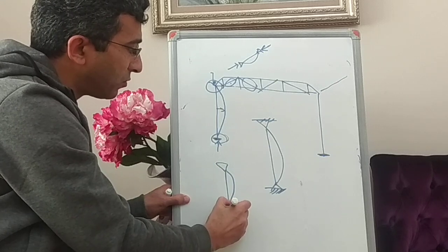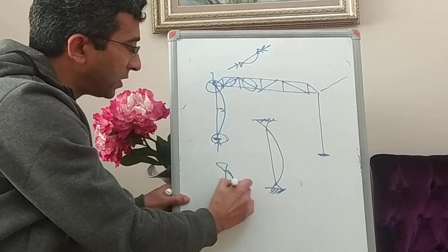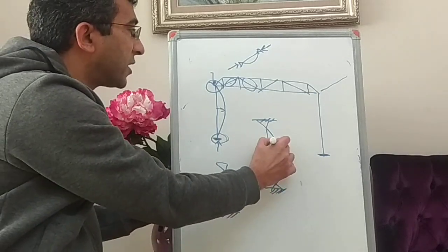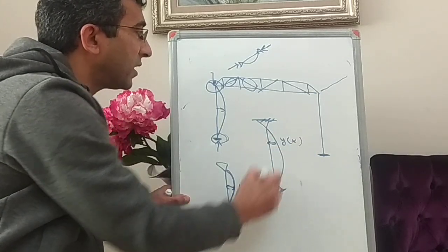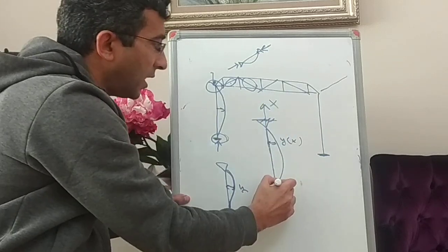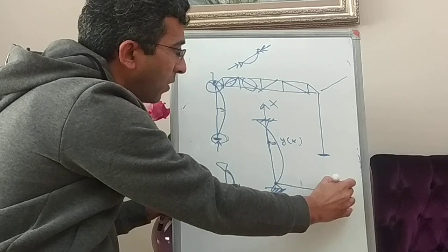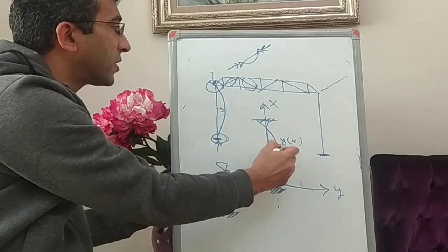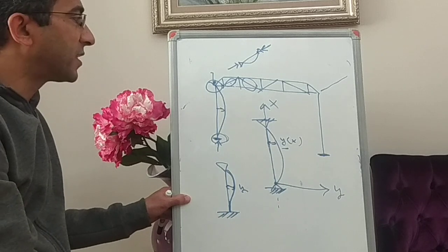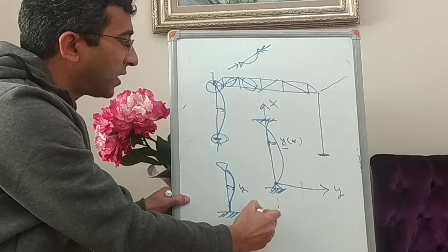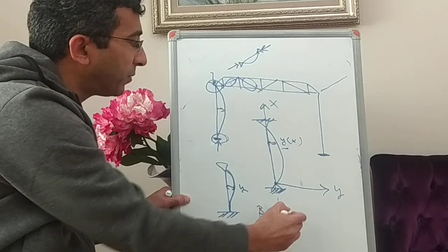Okay, so there is no rotation in this. So this is the lateral buckling. This is my y, and my y is a function of x in this case. If I call this axis the x-axis, and this axis the y-axis, my response y is a function of x, a function of the position. So we call this a boundary value problem.